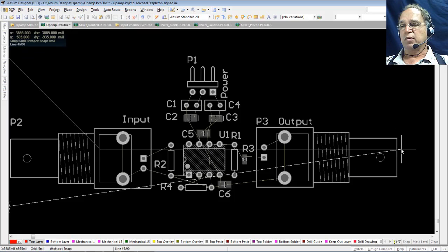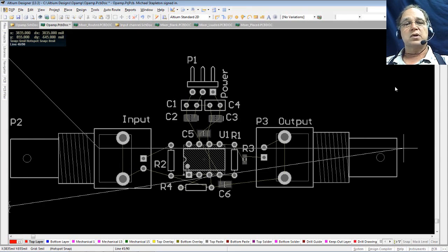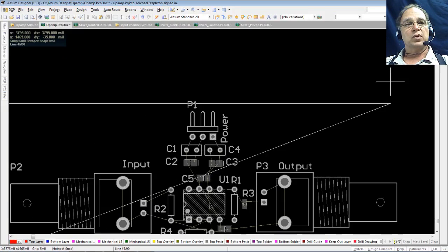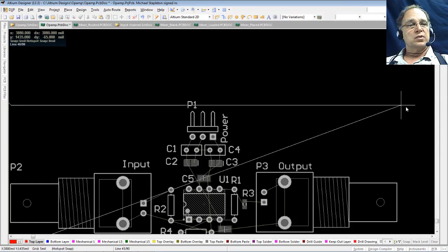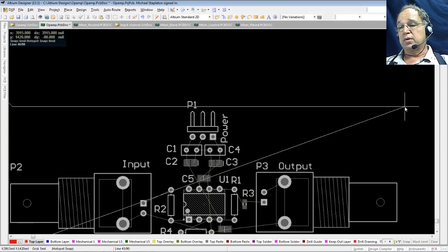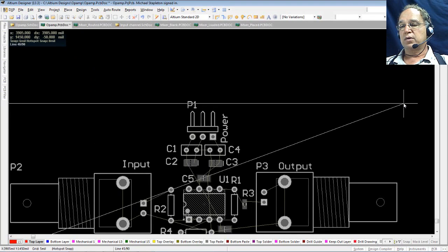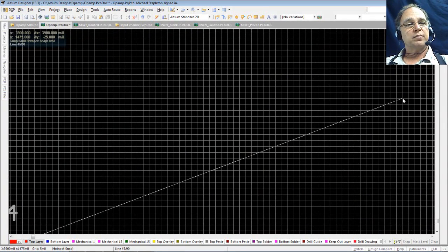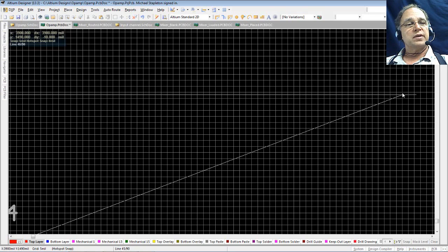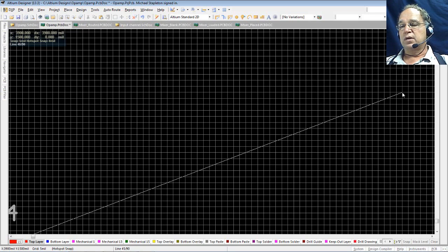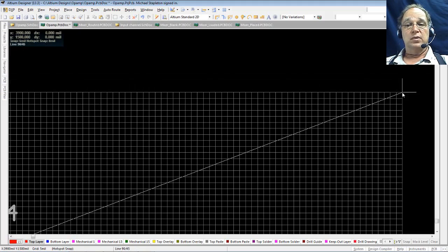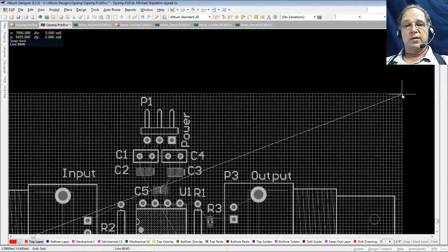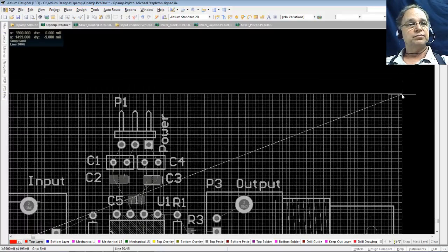Right around here somewhere. What do I have on my X? 3885, right? 3900. So I can go to 3900. That'll work. So to do that, I want to go to 3900 by 1500. Here's my X, 3900, my Y, 1475. There, 3900 by 1500. I click again. And we'll see I have 2 of my vertices set.